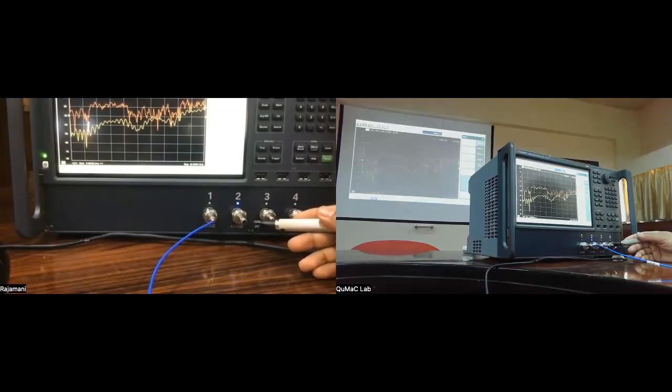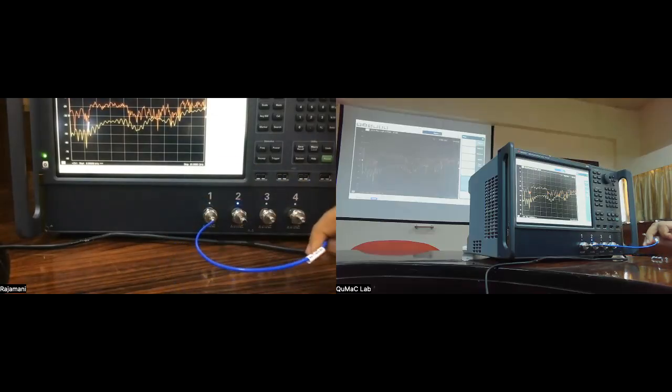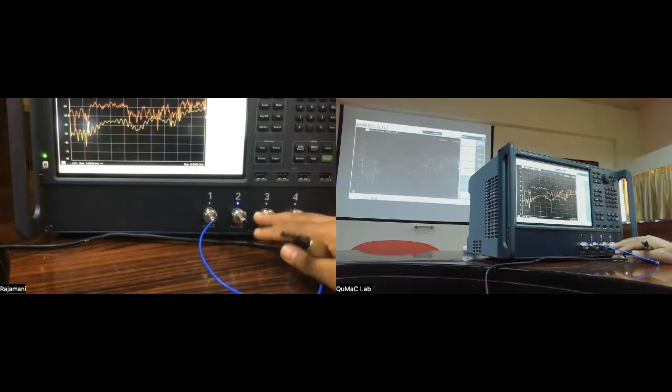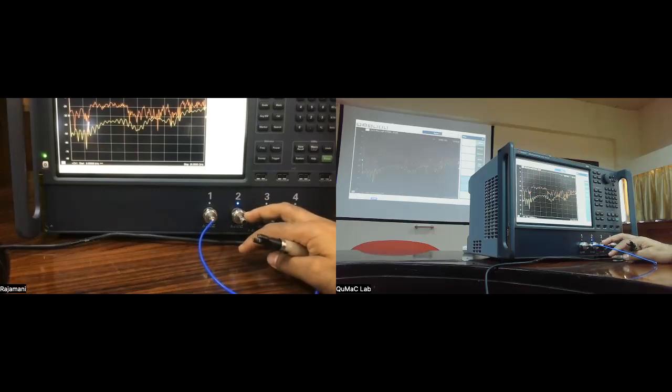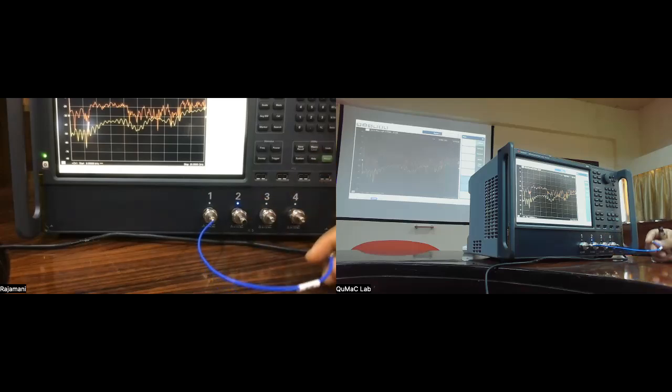So this is 50 ohm, right? So this should be absorbing everything. So should this cable be, because it's a 50 ohm transmission line, which is just delivering the power to the other side, which is also matched. So from the point of view of the network analyzer's port 2, there should not have been much of a difference. So there is clearly something different with the cable.